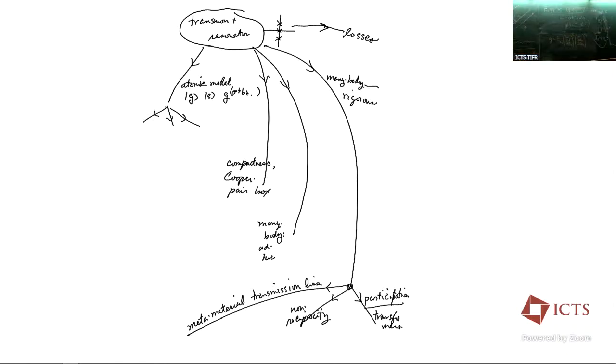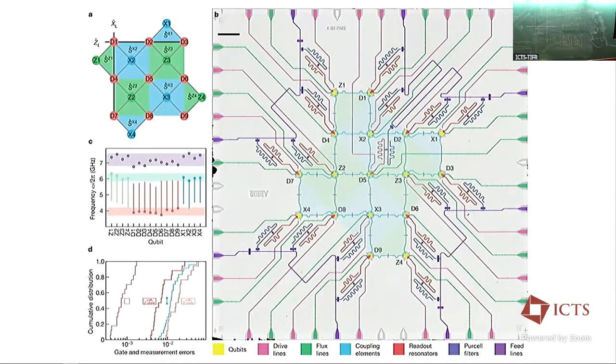I started by saying I wanted you not to forget the fact that this all came from a black box theory and a 3-pole representation of this. Now, you can very reasonably ask, what about losses? And that's not a crazy issue in the sense that these are all resting on some dielectric. Dielectrics have lossy characteristics, and so maybe that's an issue. And a thought was that what that would do is just move these poles a bit.